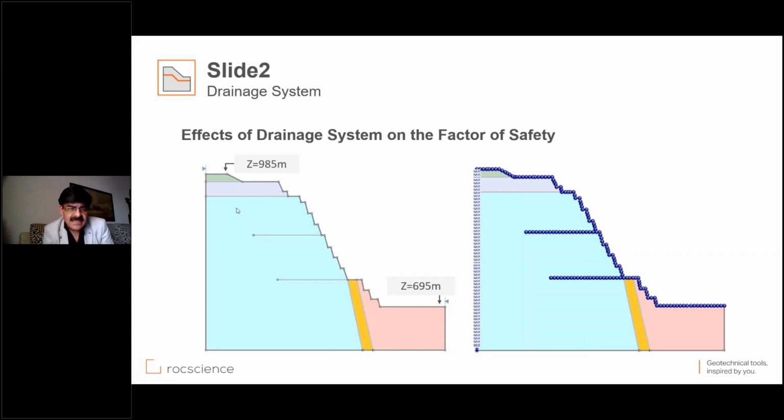So we have seen the effect of providing the drainage system on the factor of safety. And it's a crucial thing in an open pit mine in this case, but also in civil engineering slope instability problems. One of the several methods available to you for improving the factor of safety, in addition to providing support measures, is the drainage condition. And depending on how big a role the water is playing in making your slope unstable, sometimes drains can be very effective. Usually drains are effective because water has a very important role to play in lowering your factor of safety, and drains would be very useful.